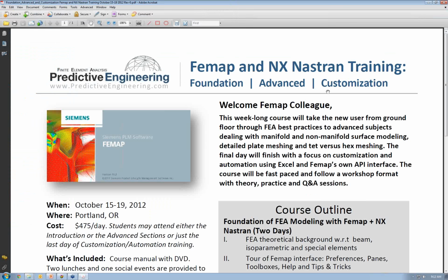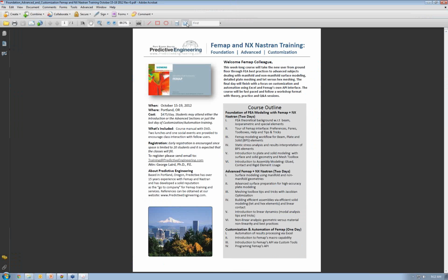And then our next seminar is going to be on buckling. It's not classical buckling, but people say, oh, you do the buckling, Larry. We're going to dig into it and talk about buckling, classical, and it's really compressive loading of structures. We want to show buckling of thin panels, and how you'd use a nonlinear analysis to assess the strength of the structure. We're going to talk about crippling, beam flanges. We want to talk about stability issues. It's a little bit of geometric nonlinearity.